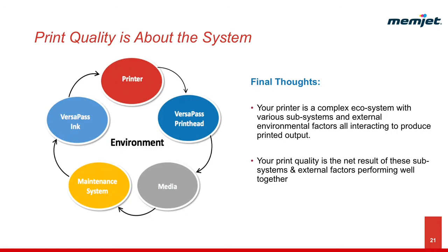If the issue follows the printhead, then likely it's a printhead issue and you need to pursue that avenue. But if the issue doesn't follow the printhead, investigate those external factors and subsystems. And if you don't have a second unit available, be sure and print out the printhead test page and contact your technical support team for additional help.